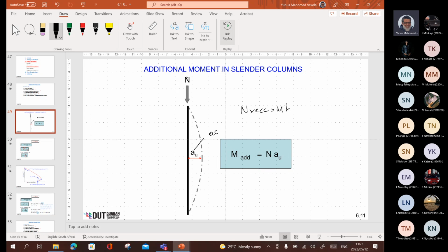Theoretically, it looks like this has just got an axial force, okay? But because that axial force now acts out here, the member is deflected to that position. Let's say it's 5 millimeters away. So the load is now acting 5 millimeters out of the neutral axis, its original axis. So it creates this bending moment.